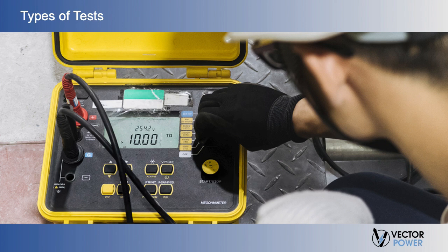When reviewing the test data, the insulation was good if the insulation resistance reading was high and if it increased or remained steady during the test. Current decreases as insulation resistance increases. If the insulation resistance reading decreased during the test, the specimen's insulation would probably be wet or otherwise in bad condition. If the final value is low or the current is high, the specimen's insulation could be better.